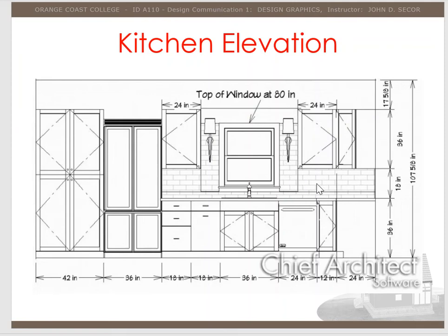So those little delicate features of the subway tile are in your lightest line. And then you have some medium lines for your cabinetry and doors. And here's just the countertops. But things that are coming forward at you are darker and show a little bit more like they're protruding forward. So we do use line weight to create depth and give it more interest.